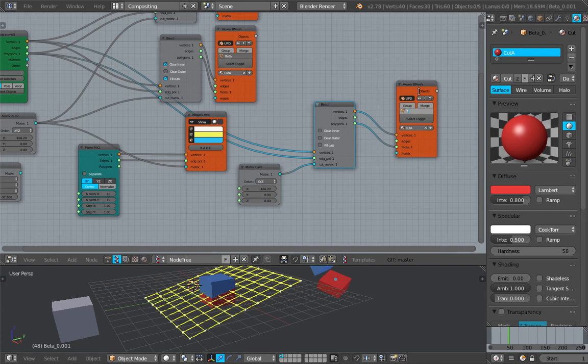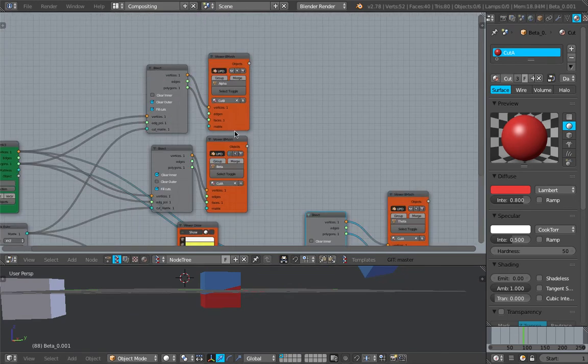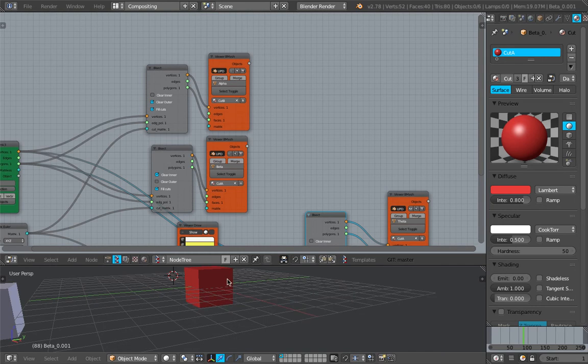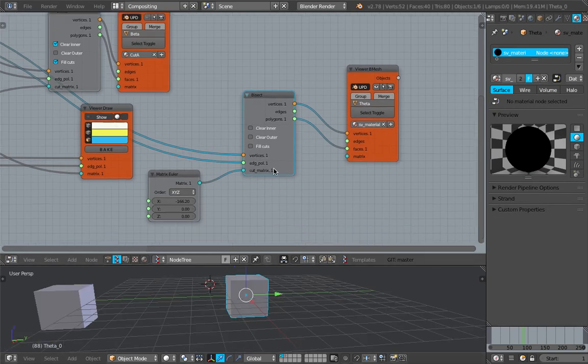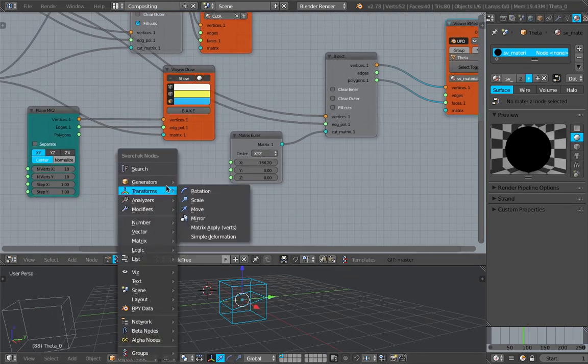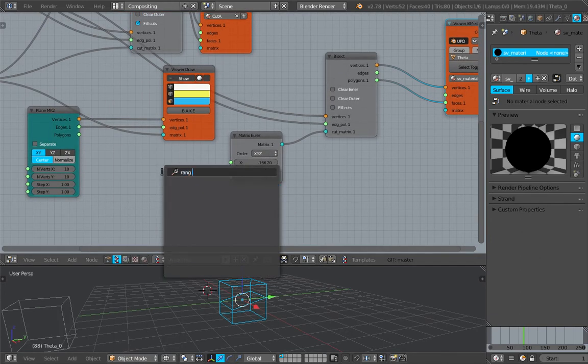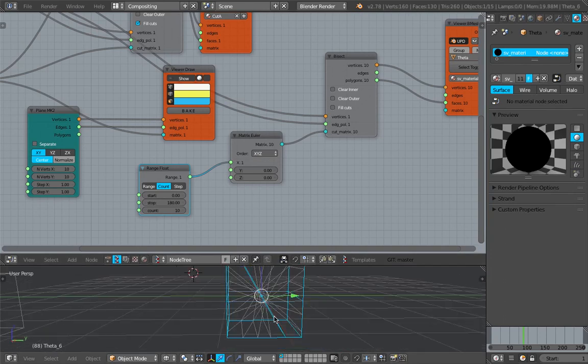Actually, cut it differently. Have a different name for it. So this guy, give it a different material. Let's try doing the cut. Okay, it's already being cut. Range float, 10 count between 0 and 360 maybe, or 0 and 180. So we have 10 cuts of the object.